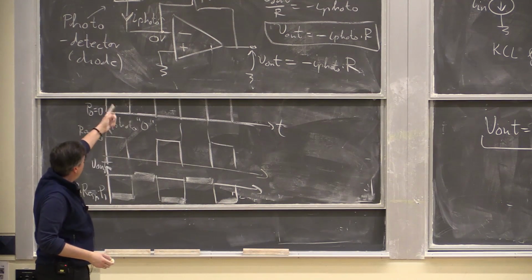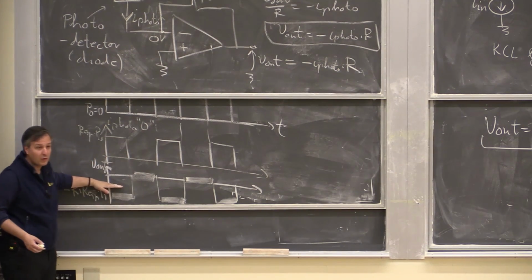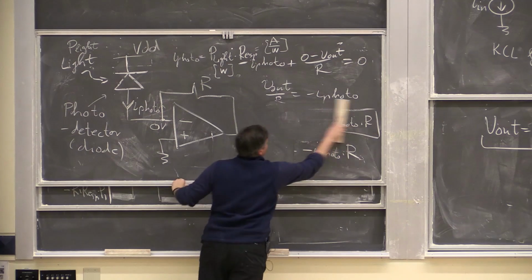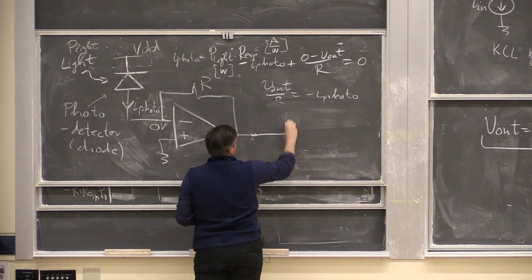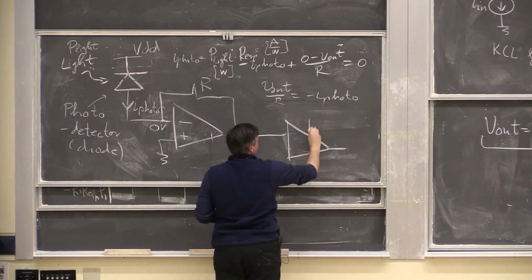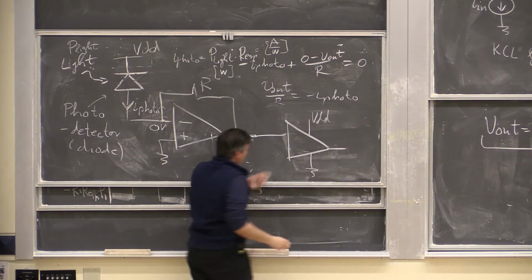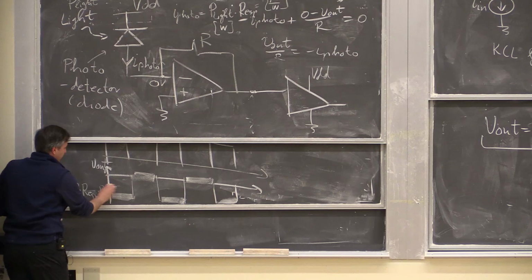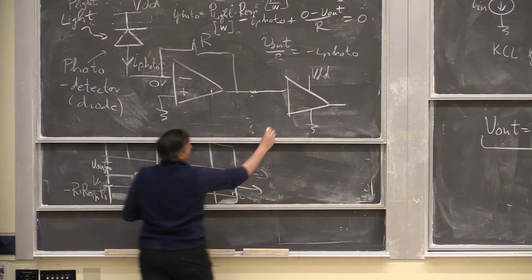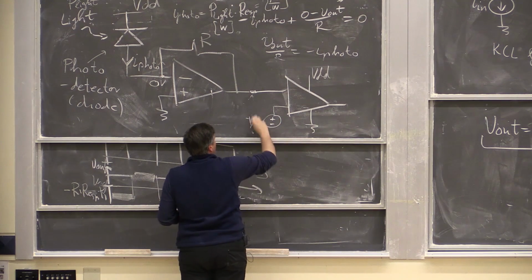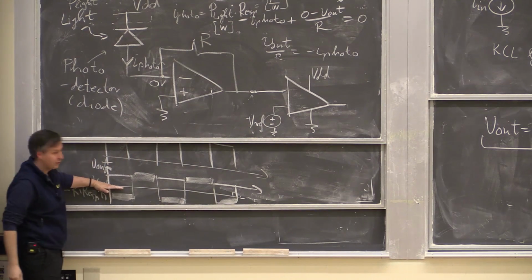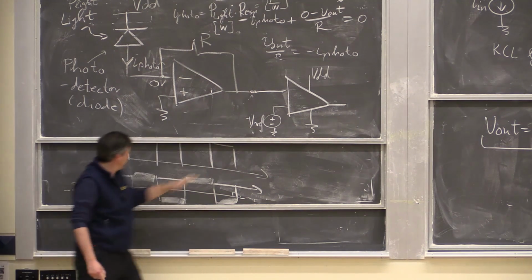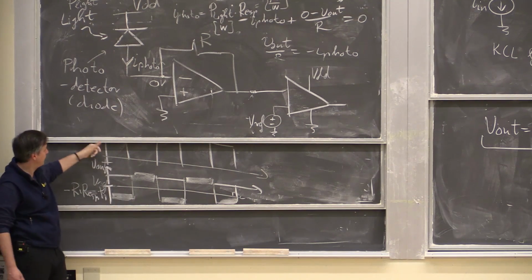What would I need after this? So I could have this basically straight into a comparator, and just set the V reference here. Right, so I could go here, put a comparator here. And then how would I hook up the signals here? I need to compare it to some V reference, which is in the middle. So there'll be some voltage here. This now has to be a negative voltage, right? But when this output is less than that reference, I need to get a logic 1, right? That was my original.